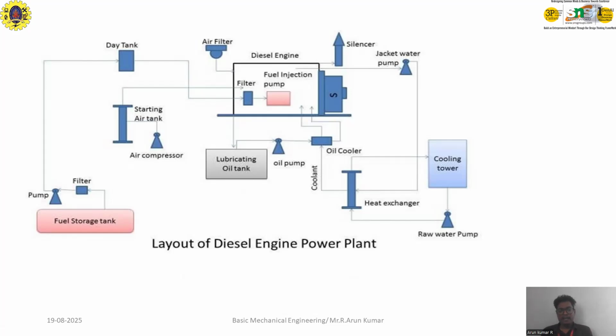The important primary thing is that we store the diesel in a particular fuel storage tank, from which it is transferred to the fuel injector pump. How is it transferred? Through filtration, you use a filter, then feed it at high speed to the day tank, which stores the minimum amount of diesel. After that it passes through a filter again and goes to the fuel injector pump. Using the fuel injector, it is burned and creates movement, and only then is the mechanical energy created.